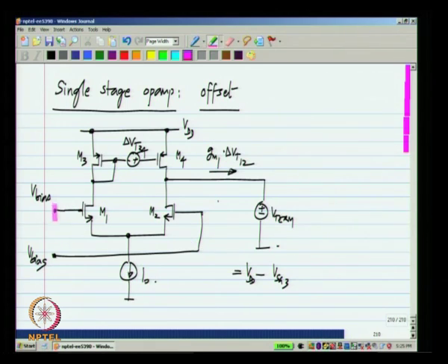Because these are at 0 and we assume that the transistors do not have any GDS, the currents in M1 and M2 will also be 0. Because of that, the incremental voltage here will be 0. Again, you can confirm this with analysis if you wish.